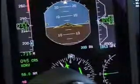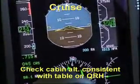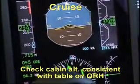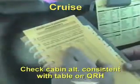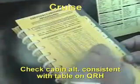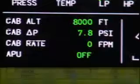Cruise. Once cruise level is established, or a step in the climb is desired, compare again the airplane cruise altitude against a target cabin altitude in the Quick Reference Handbook table. Allow the cabin to climb, or to descend, to the value read on the table. Then set null rate. Cross-check delta P.